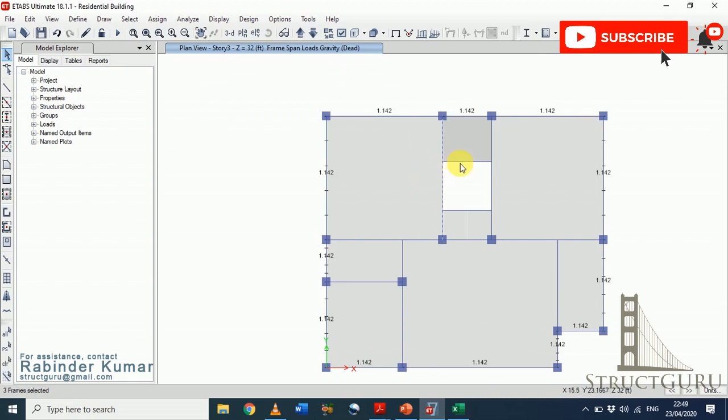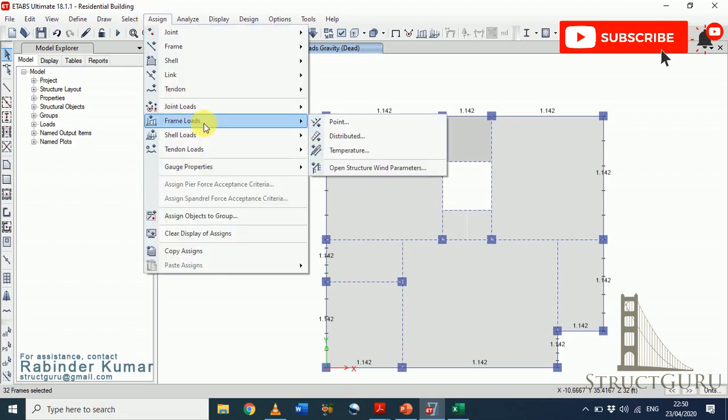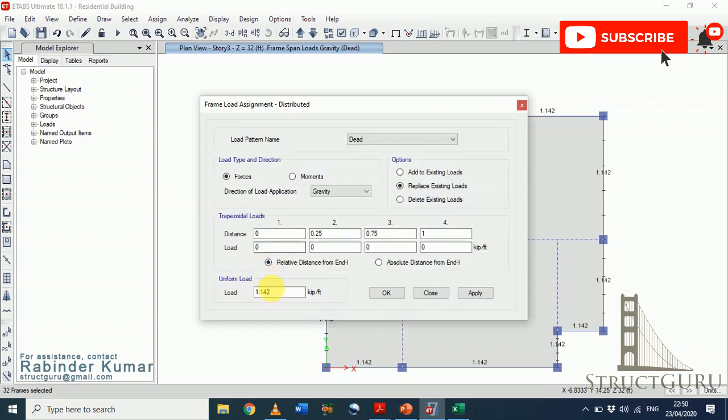Now choose the interior walls. So the thickness of our interior walls is 6 inches. So go to the frame line, again go to distributed load. Now all the data will be same except the thickness of wall, so it will be 10.5 multiplied by 0.6, which is the width of wall, multiplied by 0.145. This is the density of cement concrete block. Click enter and click OK.